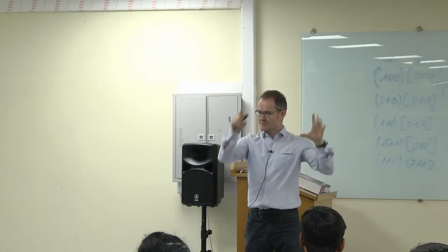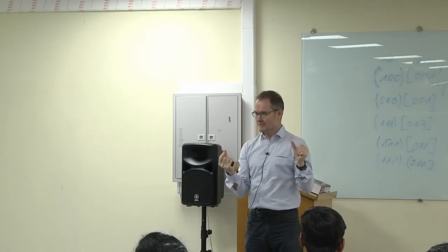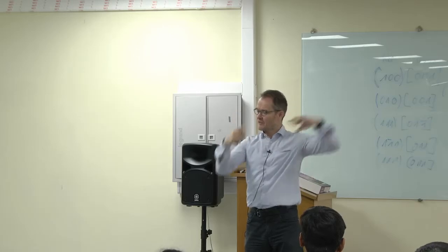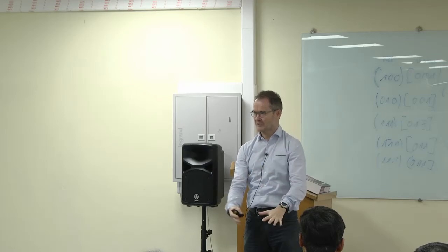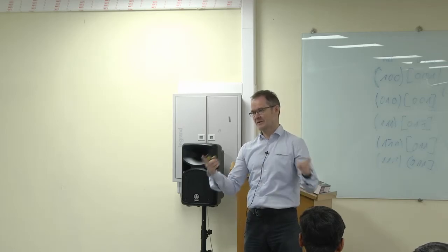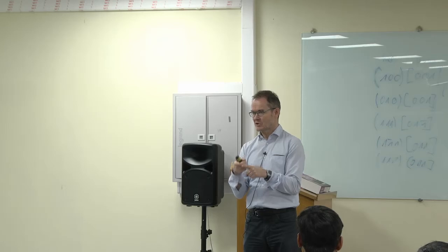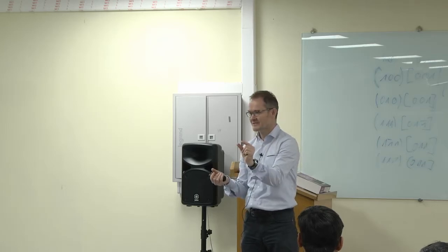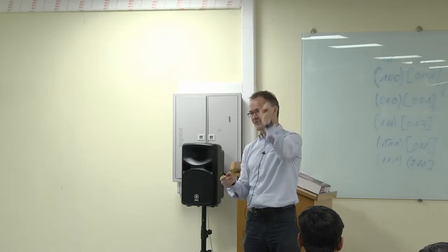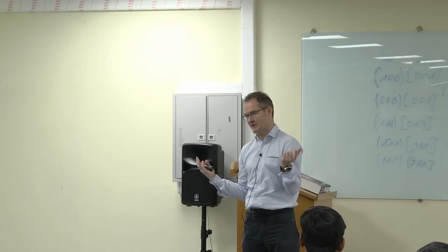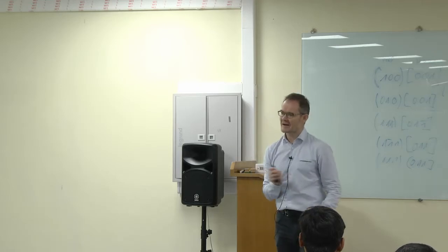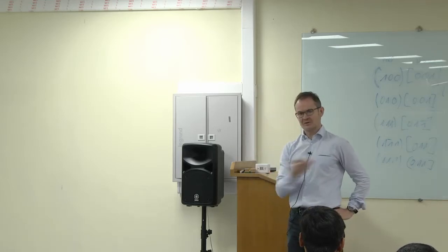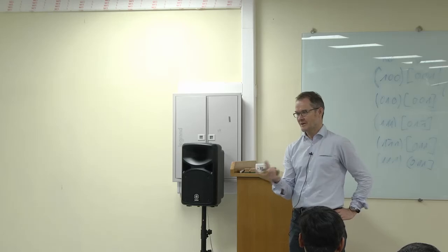You remember, I plotted points of equal misorientation, and they were further away close to capital phi equals 0, and closer together away from that. And that means if you measure just the Cartesian distance, you say it's 2 pixel distance. It's not. That depends on where you are in space, whether this is 2 degree or 4 degree. So the Euler space is in this regard not so convenient. Then you need the software which calculates how big is the misorientation.